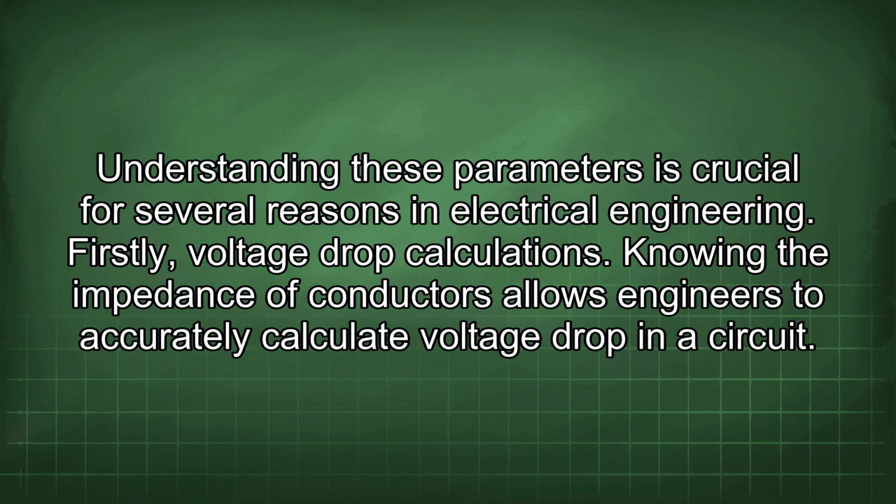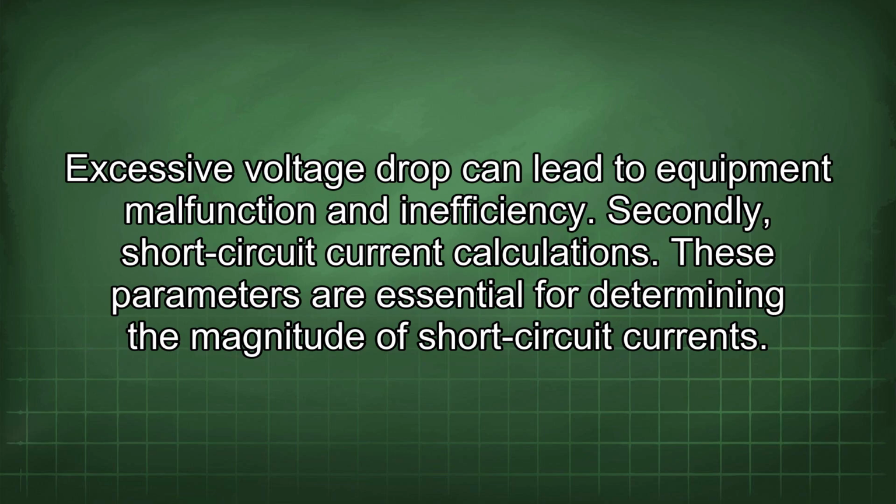Understanding these parameters is crucial for several reasons in electrical engineering. Firstly, voltage drop calculations. Knowing the impedance of conductors allows engineers to accurately calculate voltage drop in a circuit. Excessive voltage drop can lead to equipment malfunction and inefficiency.